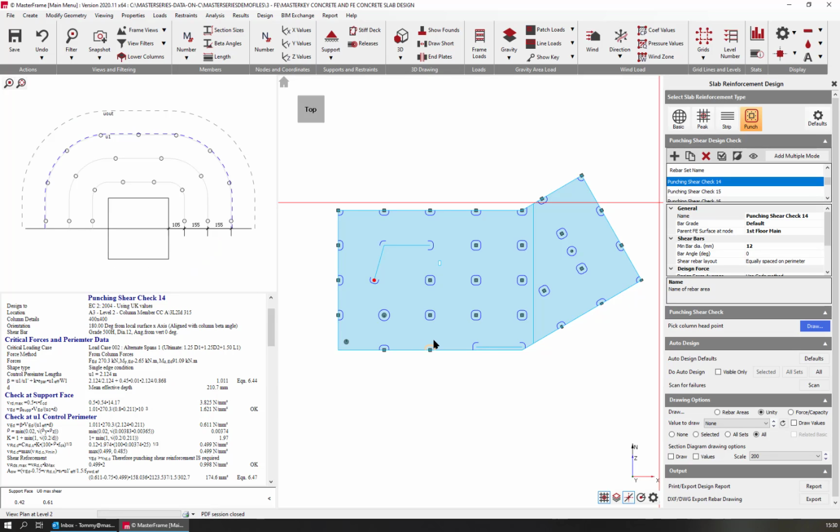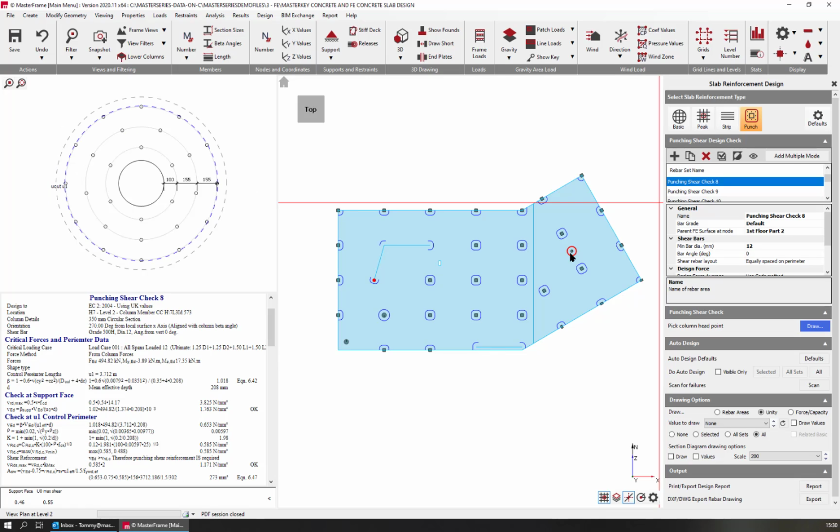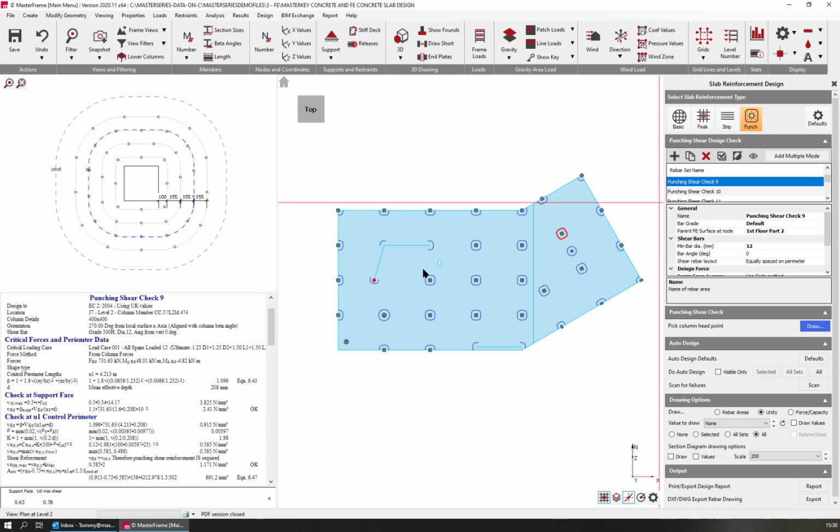At the edges here we obviously do need some rebar punching shear reinforcement, and if we look at something more onerous, something like around here, we will see it's a circular section, but on these rectangular square sections we have these bars, shear links coming in, and they're a wee bit skew, and what they are, they're equally spaced around the perimeters. So equally spaced on perimeter.